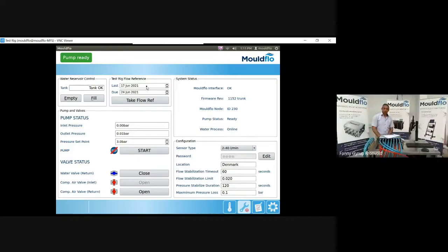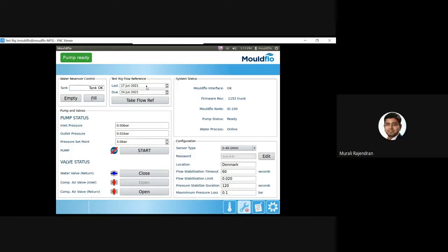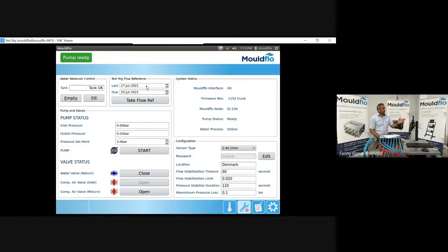Super, Murli. I have a couple of questions, if it's okay. Yes. So what you mentioned regarding the test rig flow reference, you say that this is something that we refer to and recommend should be taken on a regular basis. And what you mentioned is that if somebody banged the rig, for example, or hit it very hard, then all the components in this test rig system can be out of sync. So by doing this reference test, we create a zero point upon which the test will then be taking.